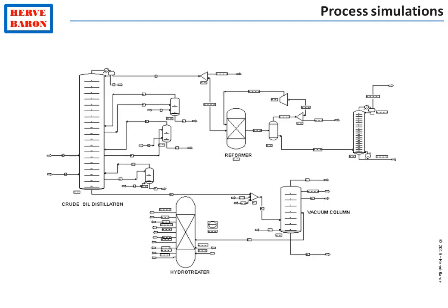Nevertheless, the process engineer must optimize the process scheme by, for instance, using the minimum number of equipment or matching the available size in the market for gas compressors and so on. Requirements such as maximum size of equipment, such as a column, might also require to be considered for specific locations.